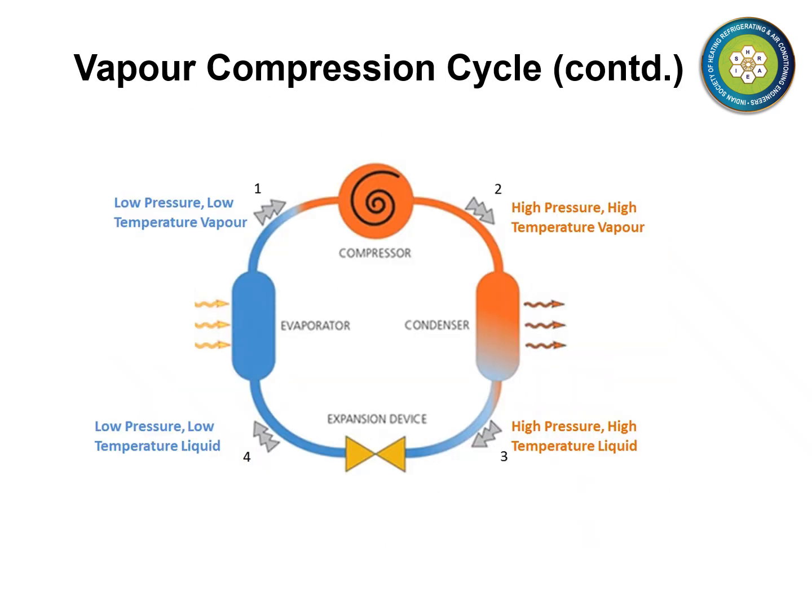This slide shows these key components and their interconnection. In each refrigeration cycle, the refrigerant flows from the compressor to the condenser, then through the expansion device to the evaporator and back to the compressor.